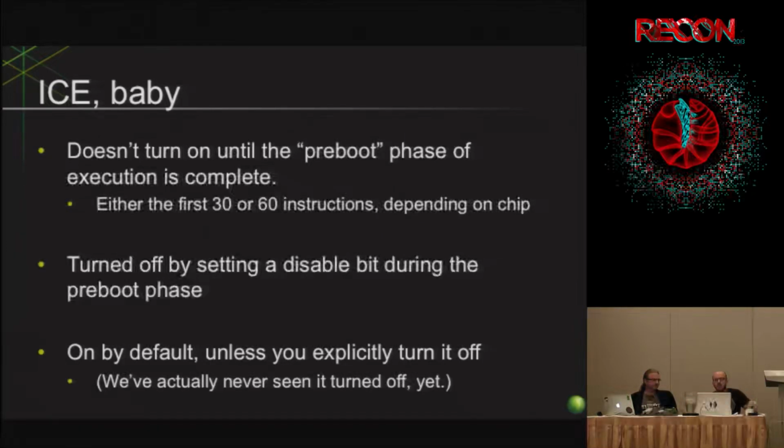It's kind of an interesting security decision, right? That it's going to be on by default always unless you explicitly turn it off. So that makes all kinds of options for how we can maybe convince this thing to not turn it off. Whereas blowing a JTAG fuse or something, it becomes much harder. You may not even be able to turn it back on at all. You may have to decap it and do some ridiculous stuff that half the people in here do, but I certainly don't. So it's much harder to turn that kind of stuff back on than it would be on this particular architecture.